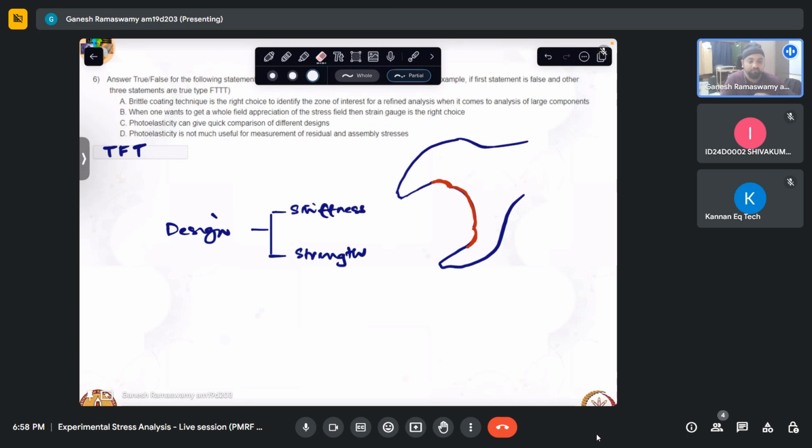Because when you have designed that component, you have assumed that these four bolts carry so much load, and they have been tightened with this amount of torque or whatever. But that is an assumption you are making based on good workmanship. But if that doesn't translate into the final component because of some manufacturing processes and personnel, then whatever stress is getting induced into the component is not the same as what you have idealized it to be. In which case there could be surprises that come about.